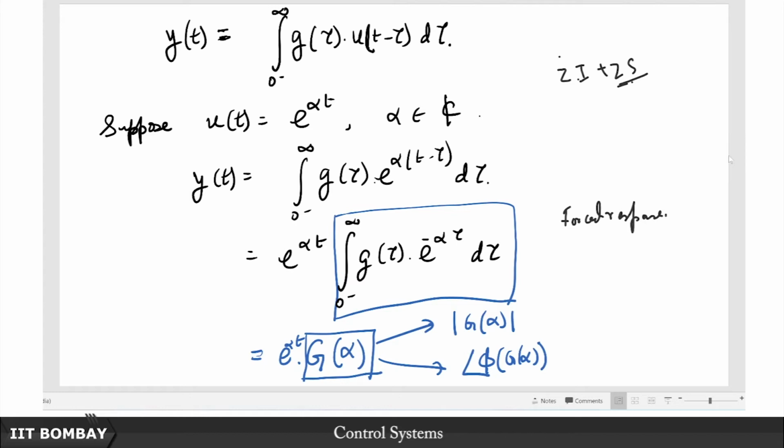So this is only going to talk about the steady state part of the response, and we shall talk about this in further detail much later in this course when we discuss Bode plots and frequency responses, but more on that later. For now, I just wanted to place it in context that you should not mistake this response for either the 0 input or the 0 state response, because it is neither. It is only one part of the 0 state response, which we call the forced response.